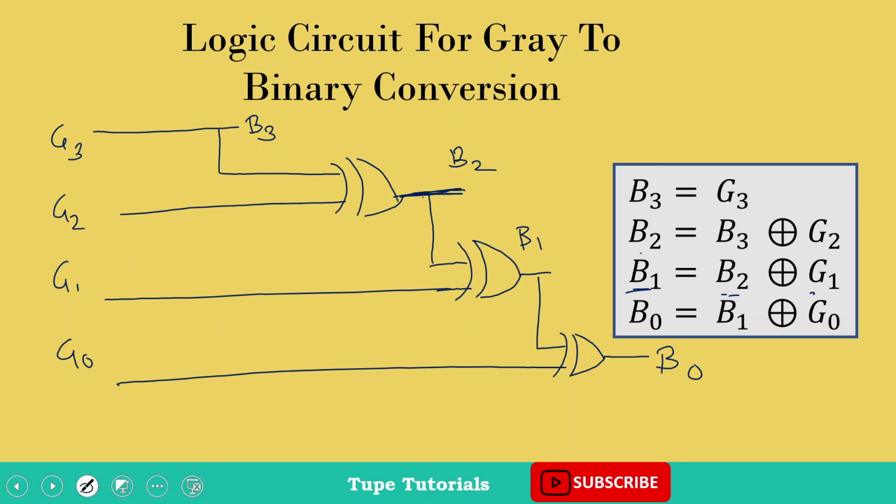So this is how the logic circuit is created using the conversion formula. So see, B3 is equal to G3. Then for B2 I have taken B3, XORed it with G2, then I got B2. From B2 I took B2, XORed it with G1, I got B1, and for B0 I took G0 and B1 and I got B0.